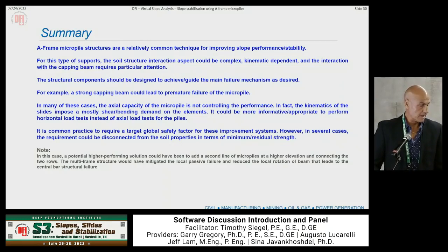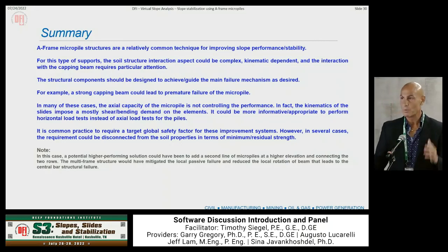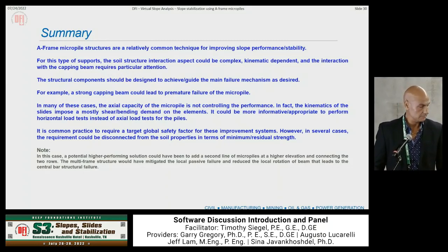And a final comment about the factor of safety. We are so used to just considering one number. We want this magic number, but there is more nuance to it. We should probably try to pay more attention to the full range of displacement. With the strength reduction, we can capture service limit state and how the system evolves and what are the failure mechanisms that are contributing to the different performance. And with that, I'm done. Thank you for your attention.